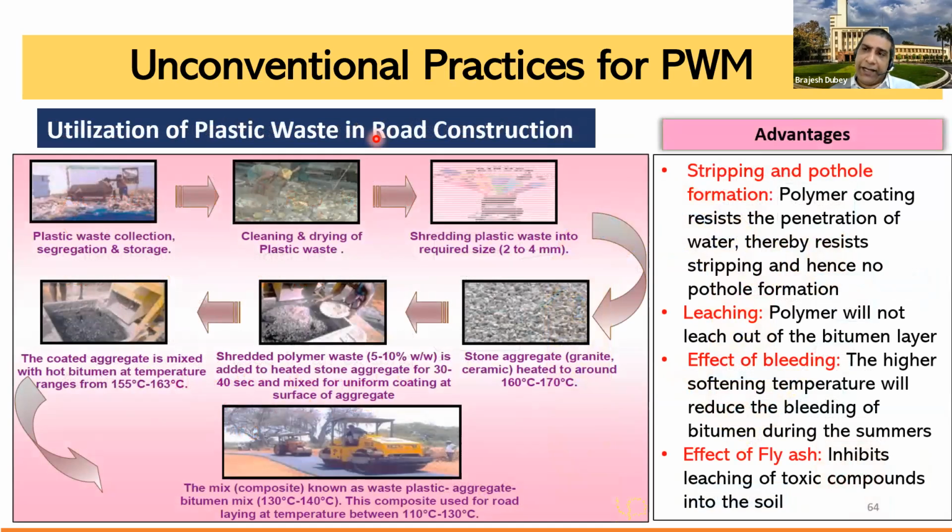Using it in road construction, again, as a civil engineer, many civil engineers in the audience will realize that if I'm using it as a replacement for bitumen in my road construction, I want it to be clean. If it's dirty, if I have to wash it, put a lot of water to wash it, and then create wastewater as well, then I may not actually be saving the environment that much. I'm solving one problem but creating another problem. We have to look at the life cycle assessment: are we really solving that problem? So that's important, we have to look at that part.